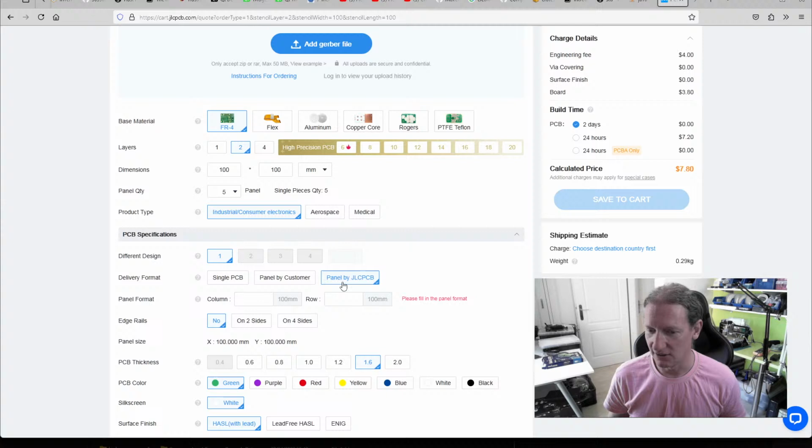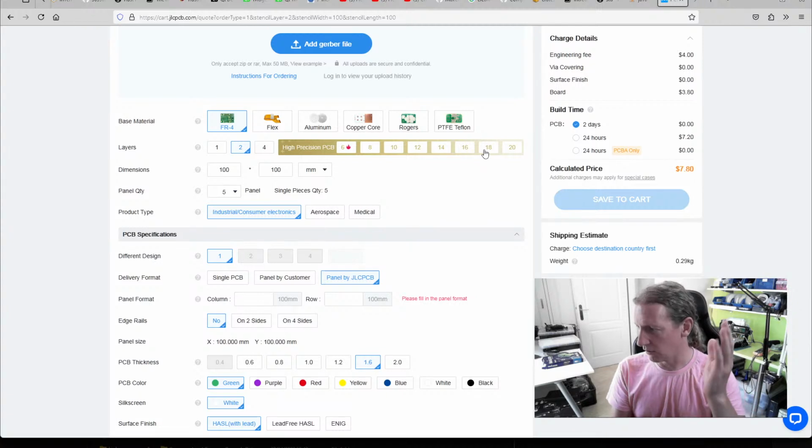So yeah, panelization. Why do we need to know about panelization? Why do we care about it? The way I do it is I get my PCB fabs, whoever they are, to do the panelization. I say I want a board with X amount on it, and I know there are various constraints on the routing. If you've got a part overhanging the edge, like a USB connector, then you need to tell them, no, you can't do V-cuts, you've got to leave a hole there, and so on. But it's normally a fairly simple process.